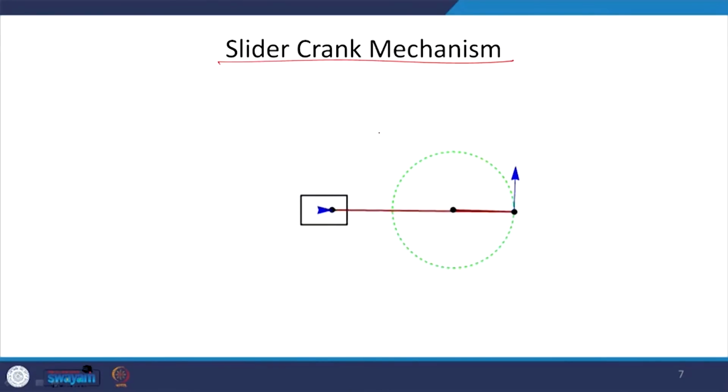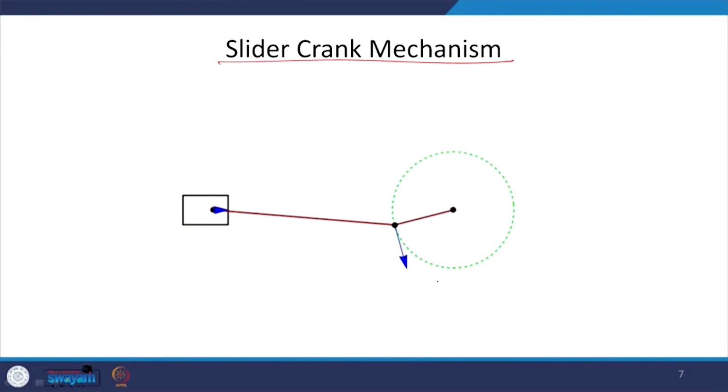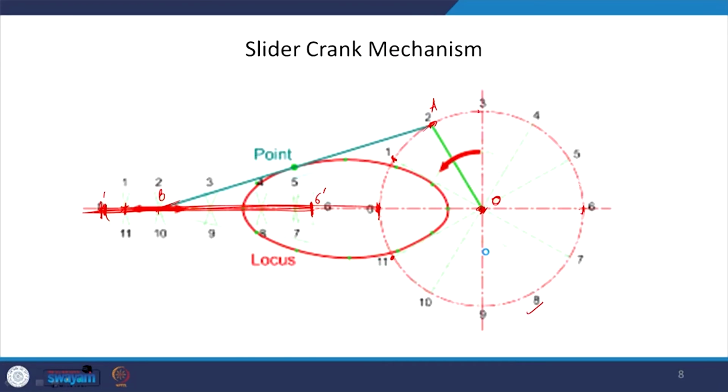Now, before I move on to explain other mechanisms, the movement here is determined by determining the locus. Any point in between on this bar A will be neither a straight line nor a circle, and the resultant will be a curve similar to a regular ellipse. So, that is what we are going to get. Here we have only figured out how it will be moving. Now, imagine it is coupled with equations where force is being applied. So, how is the force being applied?